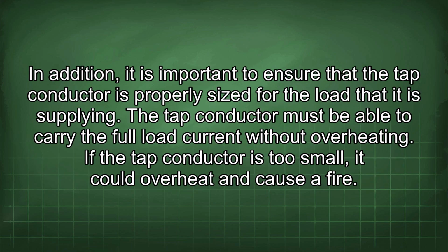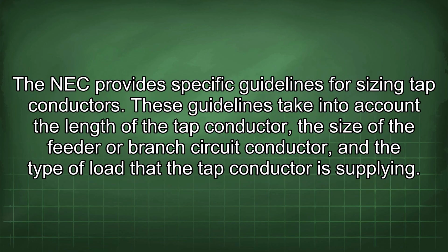In addition, it is important to ensure that the tap conductor is properly sized for the load that it is supplying. The tap conductor must be able to carry the full load current without overheating. If the tap conductor is too small, it could overheat and cause a fire. The NEC provides specific guidelines for sizing tap conductors.